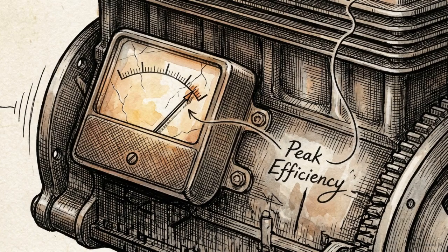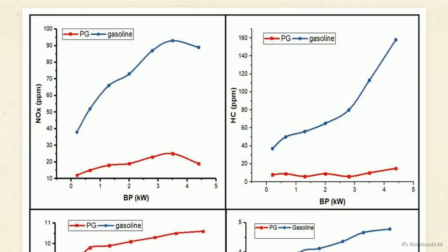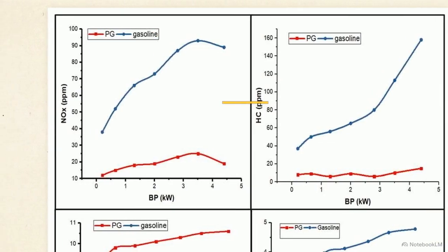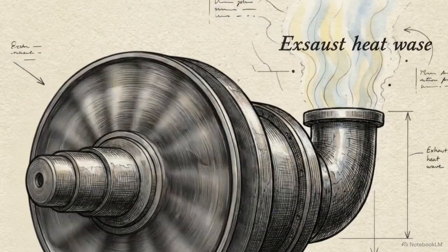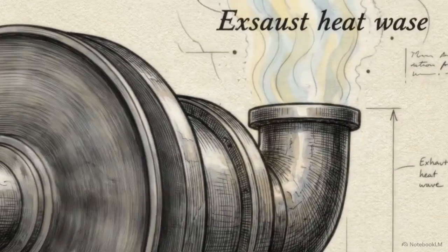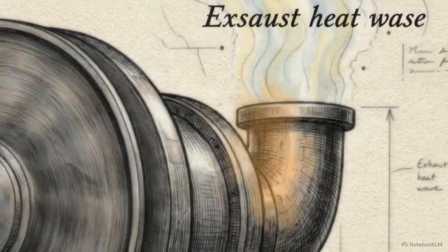These graphs map the emissions of the gasifier-driven engine in red, plotted directly against a standard gasoline baseline in blue. Because the engineered fuel has a low nitrogen profile and burns cleanly, nitrogen oxide emissions plummet. This represents an 85% drop across the load spectrum. Unburned hydrocarbons drop by 78%, and carbon monoxide output shrinks by an average of 80%. Optimizing the thermochemistry at the reactor level yields a highly stable, exceptionally clean mechanical output at the generator.